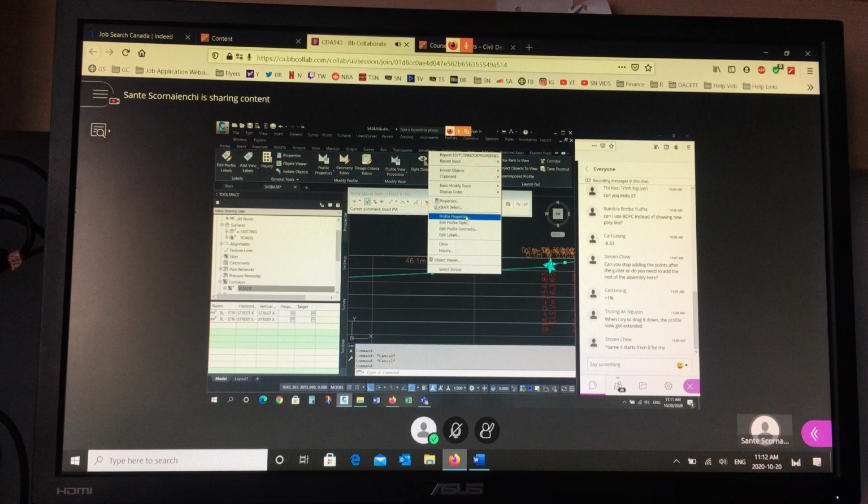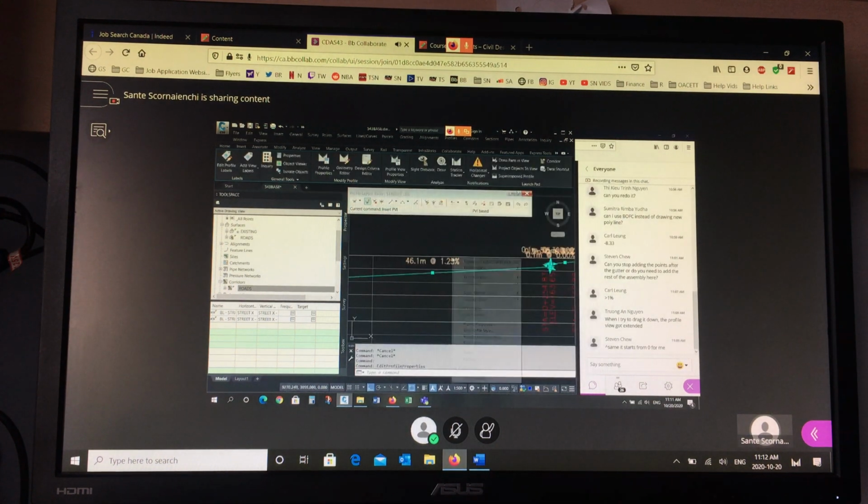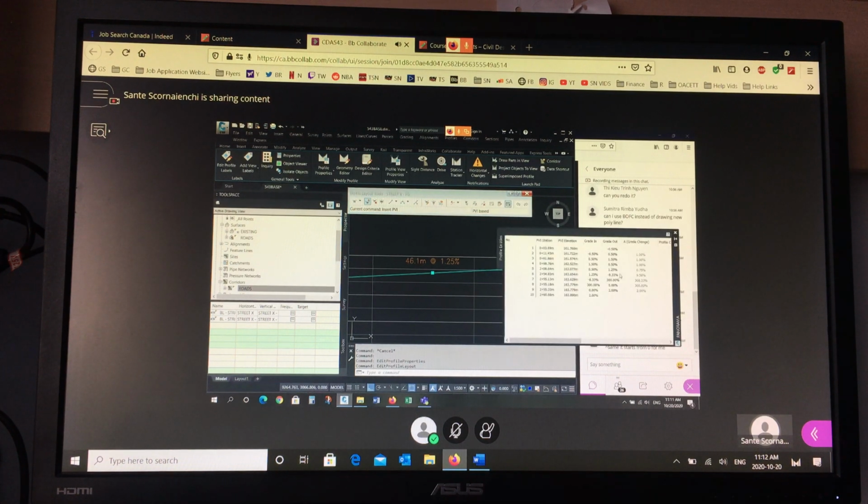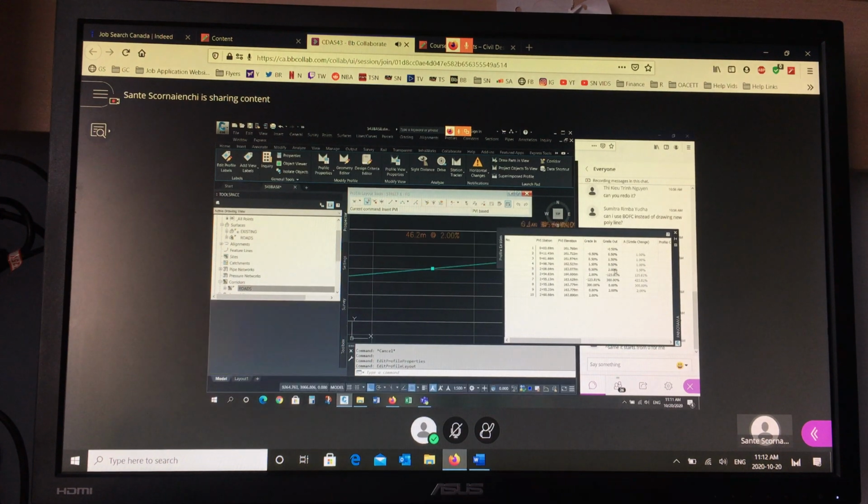If I go to properties, sorry, not properties, geometry. So now I'm dealing with street X profile, not the cul-de-sac. Instead of the 125, I'm going to use 2%. I'm going to make it much steeper. And then I have to adjust all of these. Negative 8.33, 300. Remember the last few you don't need. You only need the 833, 300, 0, 0, and 2%.